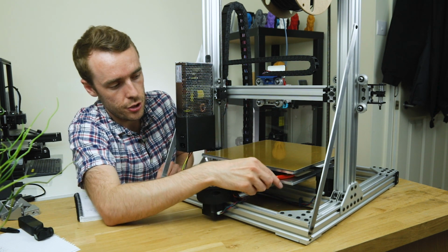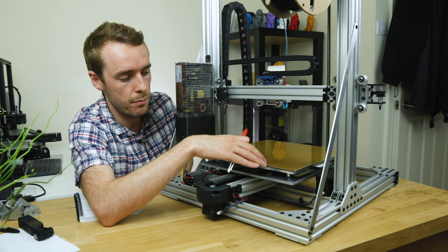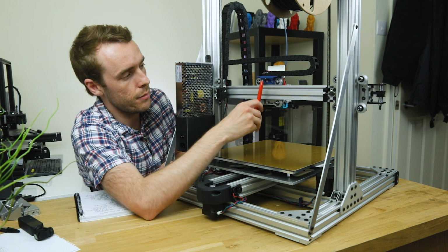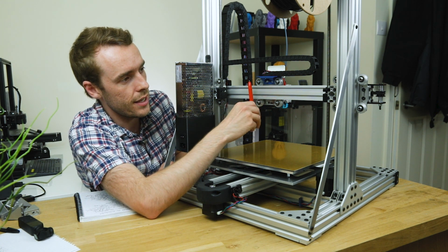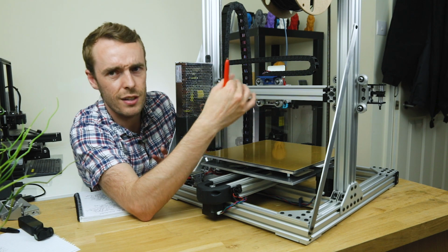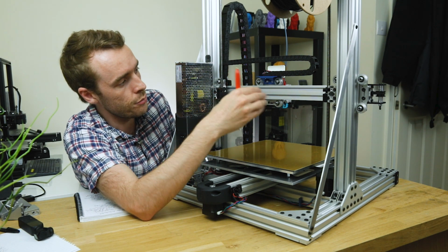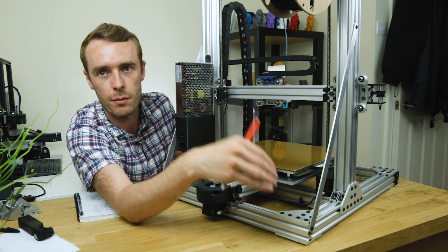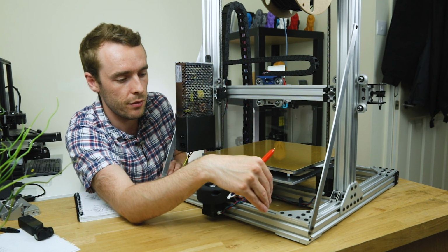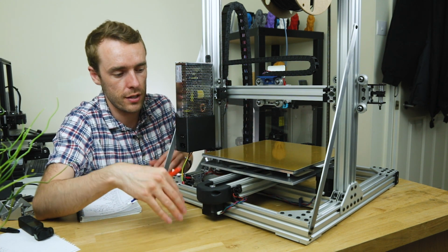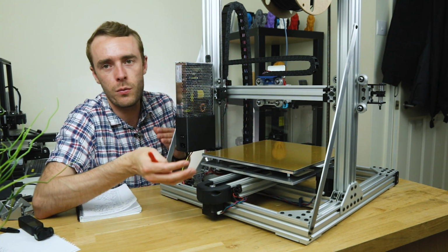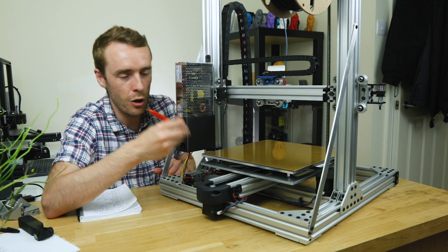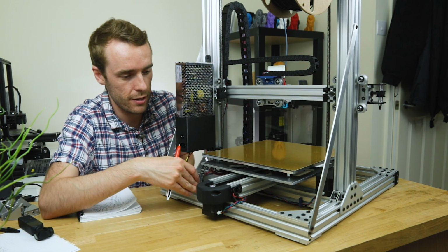What I have done is put shims in here which come with the bed kit, and that's what's designed to get the bed level. The problem is I'm obviously leveling it to the carriage, which again, I'm not sure how level that is. I don't really have many super reliable methods to get that perfectly parallel. Same with the frame. I haven't got a calibrated concrete table or anything to assemble that perfectly flat. I have got this wooden table which is fairly flat, but the problem with wood is that over time it does warp and change a little bit. So I'm just not 100% sure how square the frame is. It's pretty good.